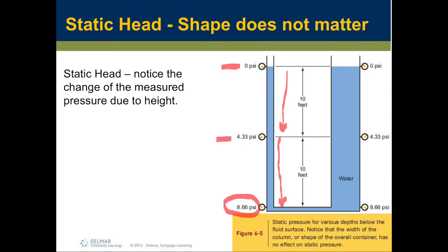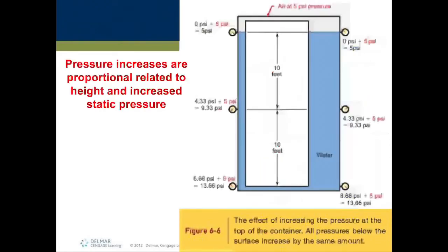Now, for this single reason, this is exactly how taller buildings and systems that have higher hydronic systems, not so much larger pipes, but taller pipes, generally have more pressure and require more pressure. This same concept is also the reason why a water tower is way up in the air. That is exactly how our systems maintain pressure in, let's say, a residential open system, where it's not a closed system, it's an actual open system.